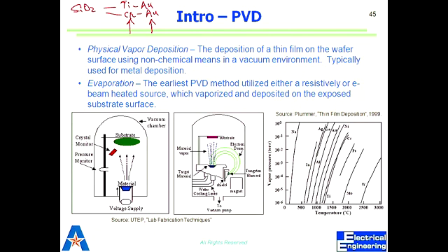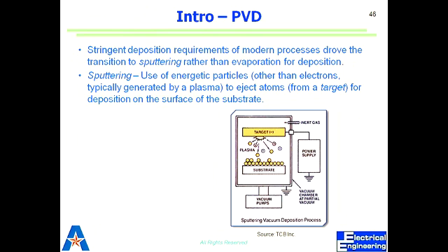So for aluminum, at 1000 degrees is where I get something like 10 raised to the minus 3 pressure. This is the pressure, and this is the temperature where I will get the vapors of aluminum. So I have to pump it down really well. This way, if I pump it down, I can get indium to evaporate at even very low temperature, right? So these curves tell us what combination of temperature and pressure is needed to vaporize something. And then once I vaporize, I will deposit it.